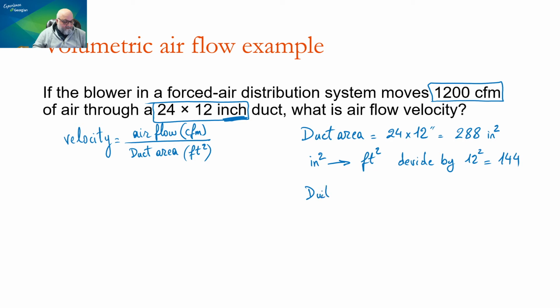Duct area then equals 288 divided by 144. It's 2 square feet. That's it. That was the whole measurement we're looking for.